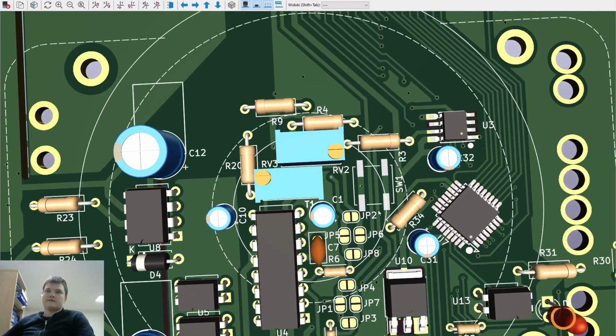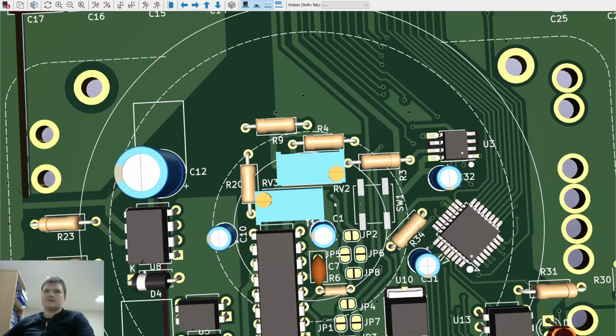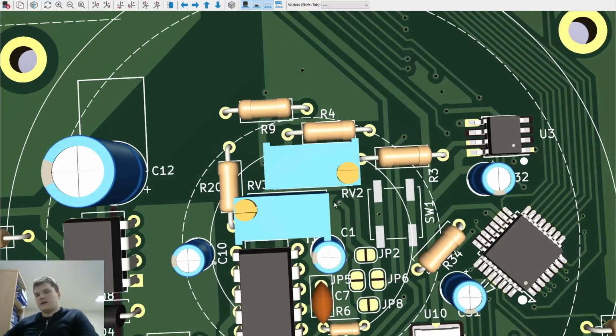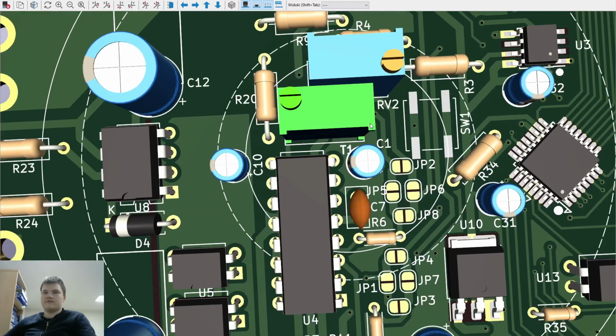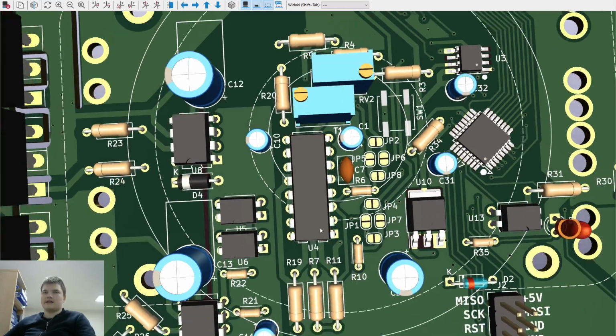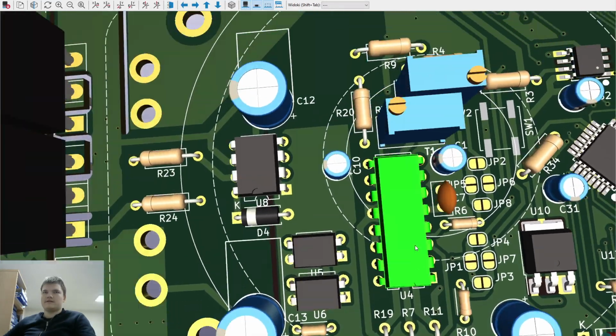and here you can see the reset button. You can see the 2 potentiometers that regulate the voltage division. They are basically for regulating important voltage dividers that feed voltages into the comparators inside this switching IC.